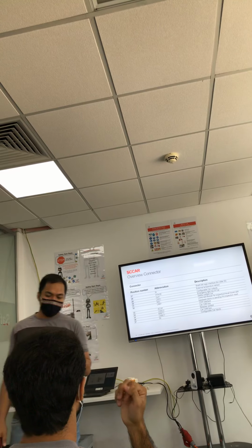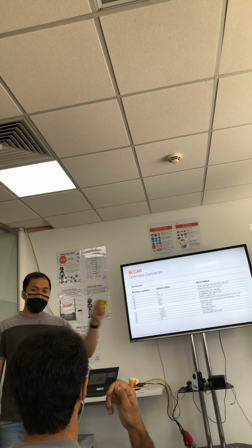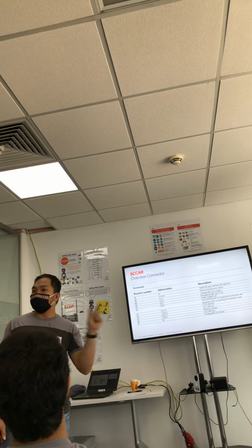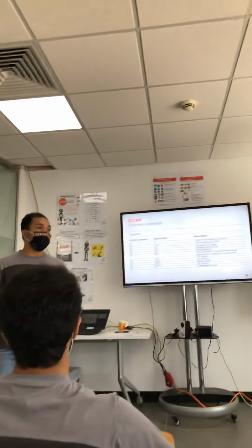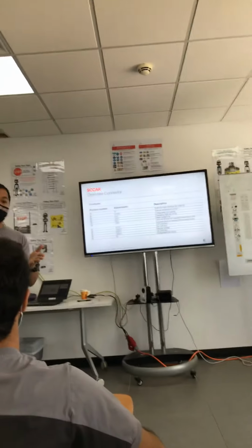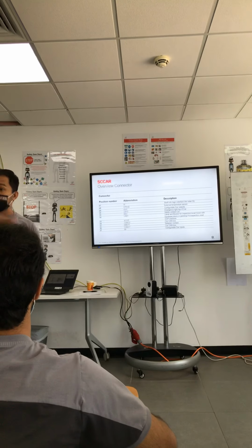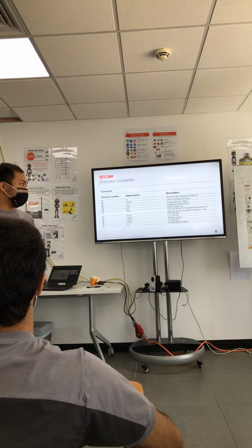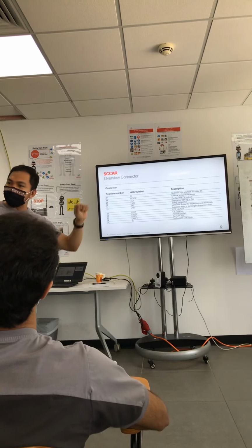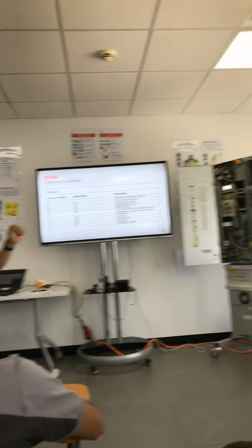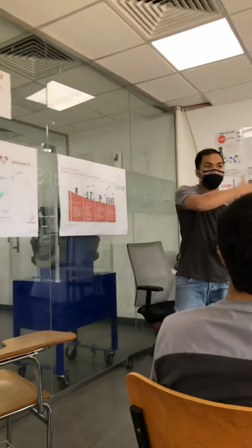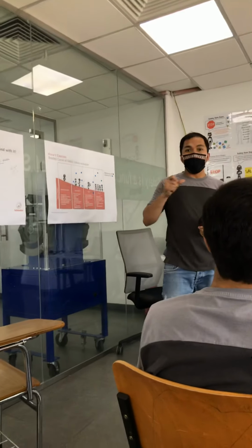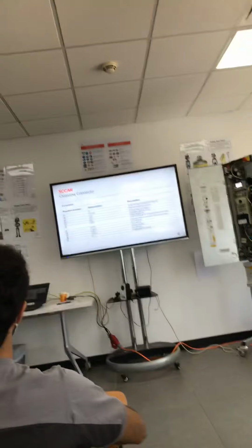The good thing here is if this is not the right one for this plug, it doesn't go in. That's why I always tell the maintenance people or the installation team that if they plug in or plug out, your power should be switched off. Just in case the power is on and they put in the wrong one, and then boom, burst.